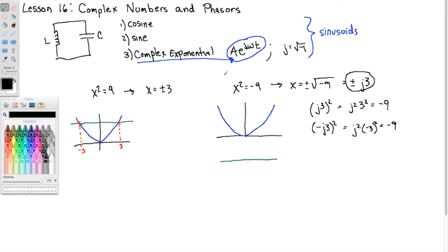So just a little definition here: j is the imaginary unit. You may have used i in high school or in some college courses, but we don't use i in electrical engineering because we use i for current. So we're going to stick with j. Now when a number like 3 multiplies j, we're going to put that to the right of j like I have here. It's kind of weird and takes some getting used to, but that's what we're going to do. This signifies to the reader that this is going to be an imaginary number, right away.